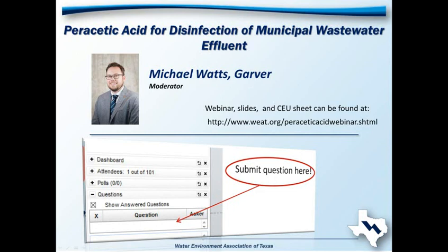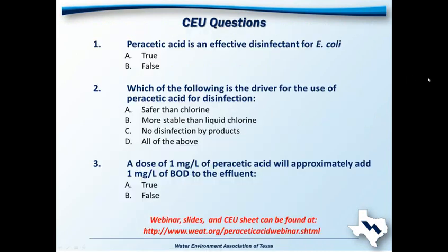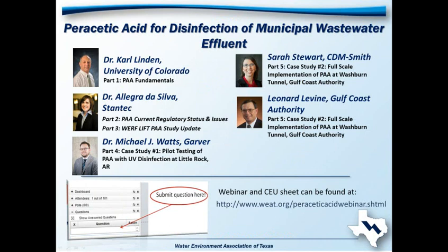This is LRWRA. I mentioned on one of our slides we have two publications looking at MS2 bacteriophage and mouse norovirus. This was just on one wastewater, Denver's main wastewater treatment plant, Denver Metro. In that wastewater, PAA was shown to be similarly effective at inactivation of MS2 compared to monochloramine. So we didn't see a problem with virus disinfection if MS2 bacteriophage were the EPA recommended viral surrogate. We saw somewhat different results for mouse norovirus, which is a surrogate for human norovirus, in that it seemed to be more susceptible to monochloramine and less susceptible to PAA.